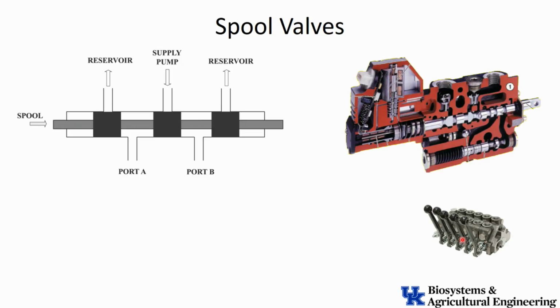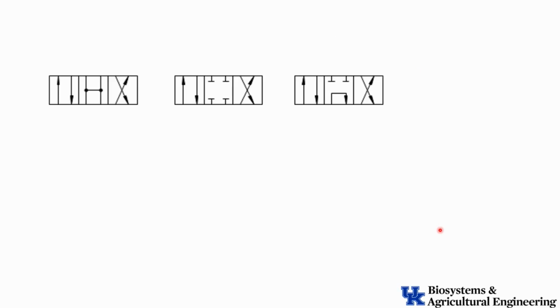They're all stacked together, and this would be nice because I would usually connect the pump supply to one end of this stack. The oil would go through that stack. The return to the reservoir, the tank side, is on the other side of the valve stack. And then each one of these pairs of ports on the top would be my A and B for whatever I want to actuate. So I could actuate a number of different systems with that, different actuators, simultaneously and so forth. And we'll talk about what happens if we try to do them simultaneously.